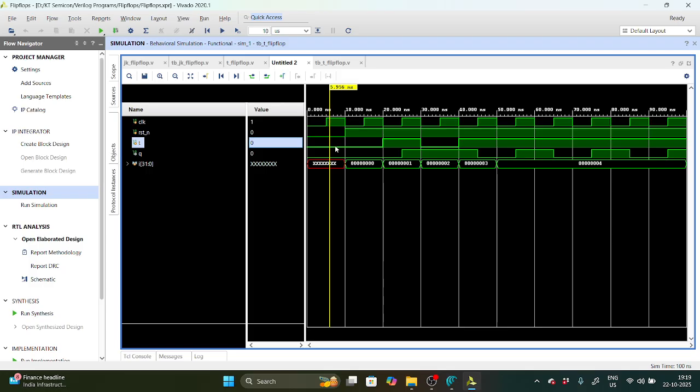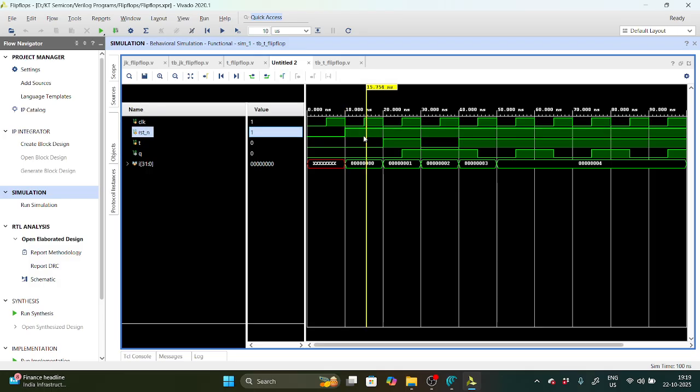So the reset will be in active state. So that means here reset is going from where to where? Reset state to reset mode to functional mode. Okay, so when it is going from reset mode to functional mode, this is not asynchronous. This is synchronous with the clock. So here during passage of clock only the output will change.